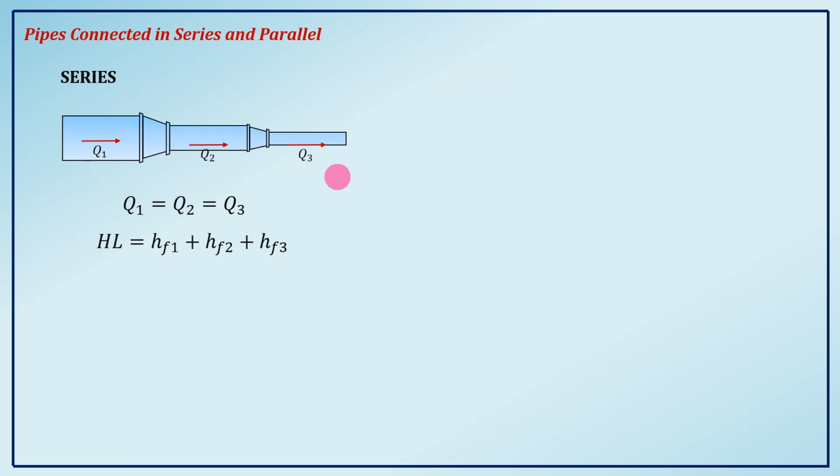Changes in elevation, the pressure head, and the velocity head can also contribute here. So, we cannot forget Bernoulli's energy equation when we're analyzing series pipes.